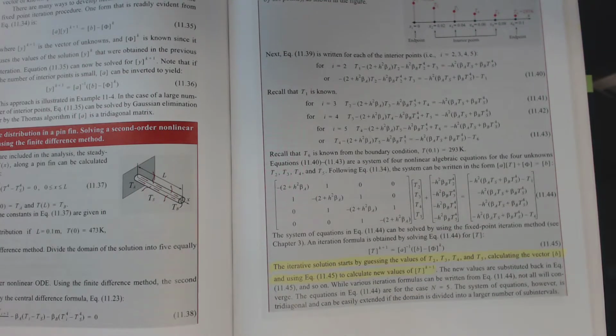So the solution method here is you have to use the iterative solution. You have to solve essentially for the unknown value T and then just iterate through and hope it stabilizes. If you need to numerically dissipate some of the instability away, please do that. Relax the problem numerically by only taking a certain percentage of the indicated step. If the next iteration says you should increase T2 by 400, relaxation of 30% means that you only take 30% of that 400 step. And that can massively help to stabilize a numeric system.